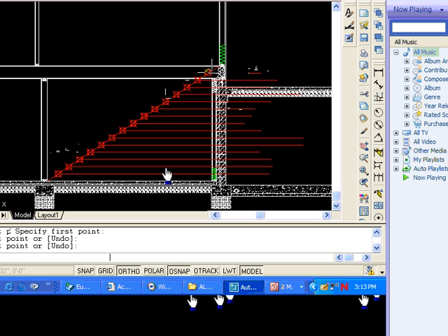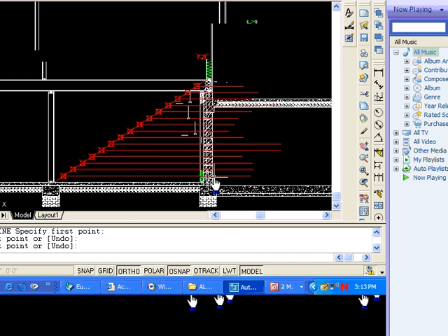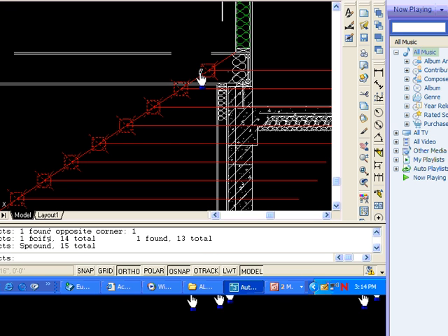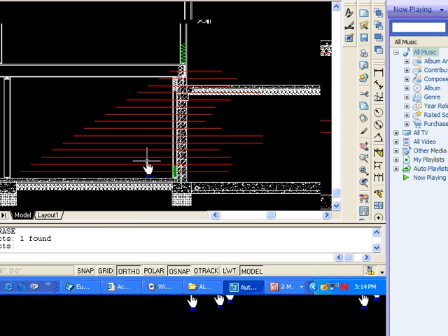All right, so now I have these construction lines here. For all practical purposes, I can erase all of these nodes now. I think I'll just do a window for a good chunk of them. I won't need any of them any longer. I won't need that line either. So what I have is 16 evenly divided spaces.